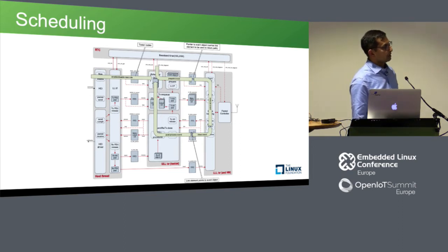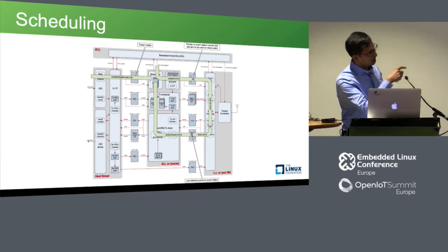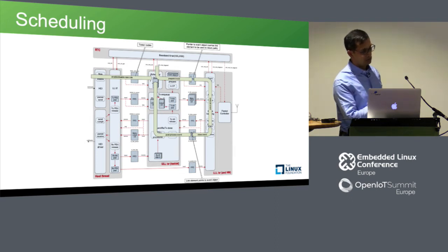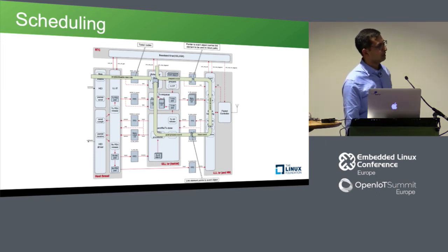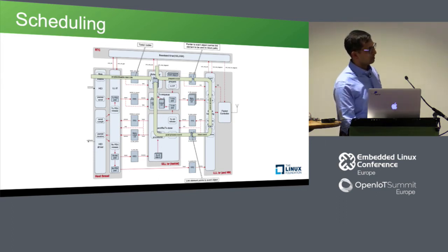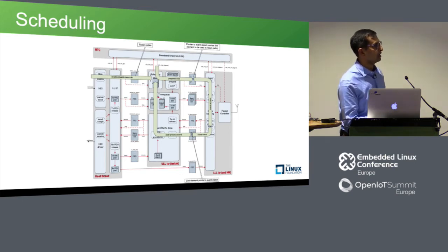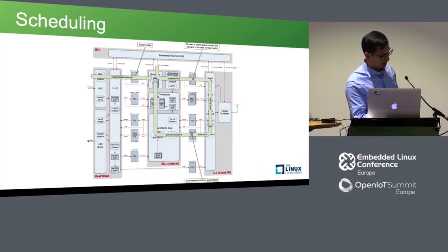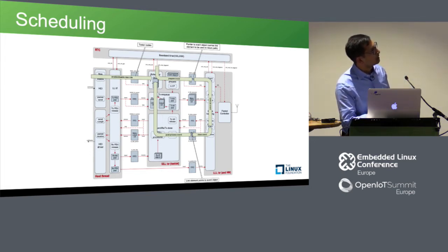So what's happening on the scheduling in the new architecture? You can see the bigger blocks are the execution context. There's the host, and in the center you have the upper link layer, and then on the rightmost side you have the lower link layer. When you want to start advertising, the API from the application would then translate into HCI. Okay, so this is the HCI. HCI would then call the link layer interface to prepare a scheduling message that's placed into a queue here.